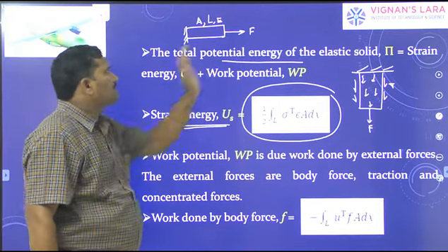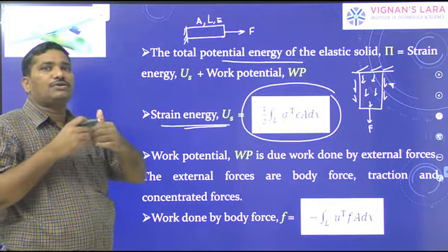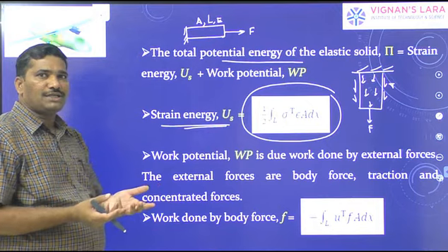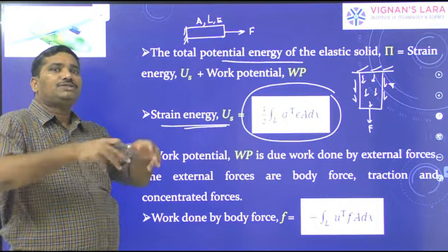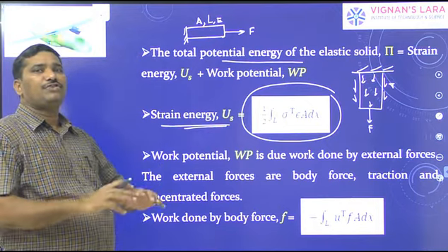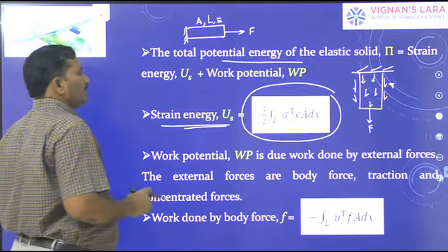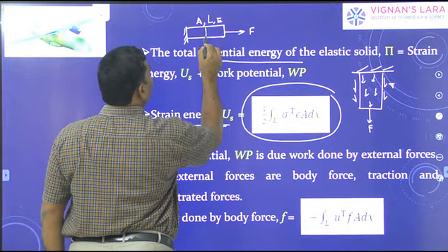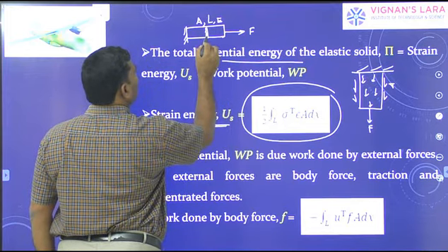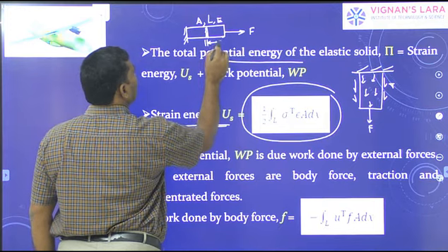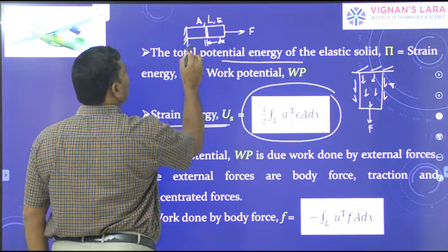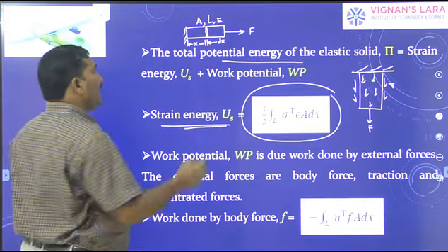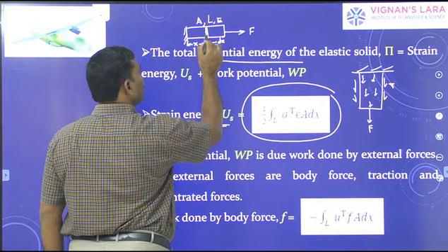Okay. Under the action of this force, this bar undergoes deformation. Right? Now, due to deformation, what happens? The energy is stored in the object in the form of strain energy that I determine. How do I determine? See here. If I consider an infinitesimal element of thickness dx, distant x units from the fixed end, what is the energy stored in this infinitesimal element?